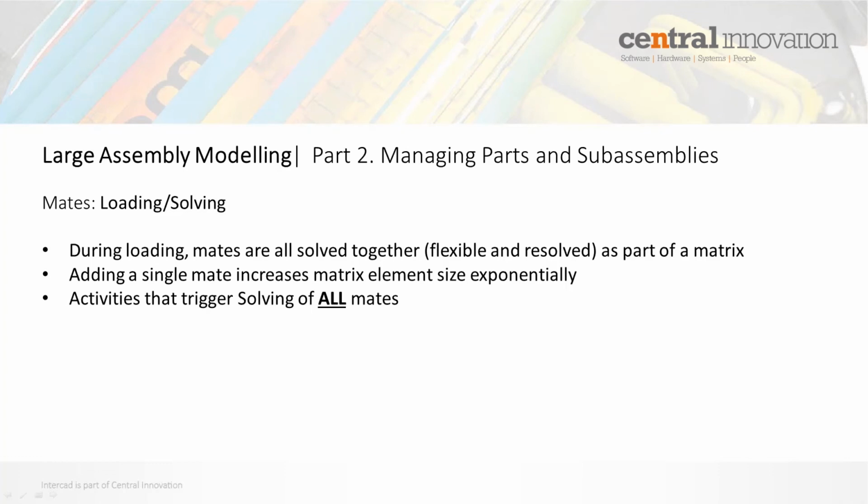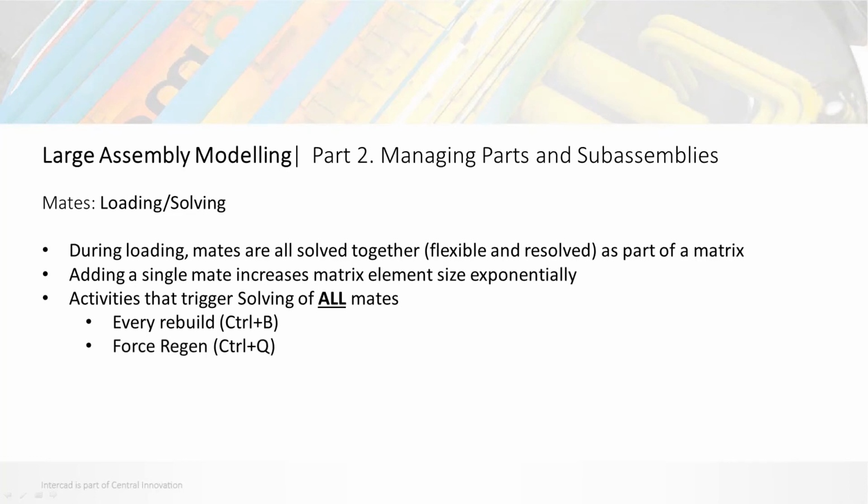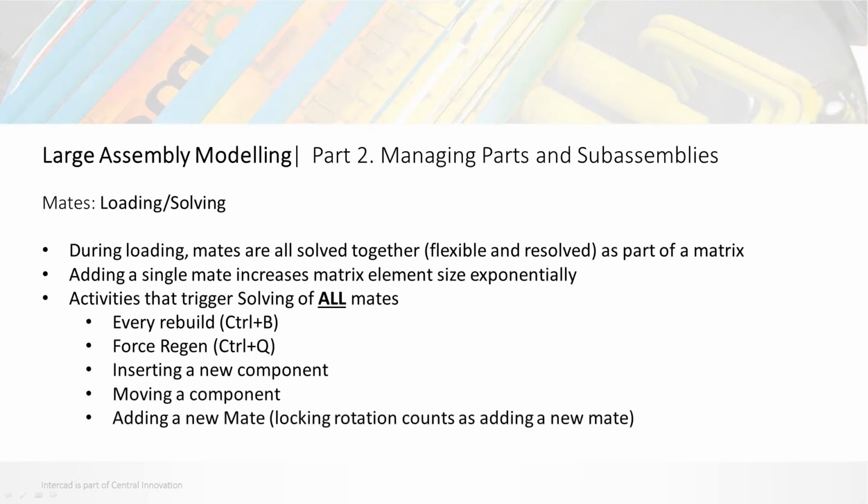Some of the activities that trigger solving all of the mates, and you might find this list quite surprising. Every time you rebuild the assembly, you're going to solve all of the mates. Every time you force regen, Control Q, you're going to solve all of the mates. If you insert a new component, you'll be solving all of the mates. If you move a component in the assembly, you'll be solving all of the mates.